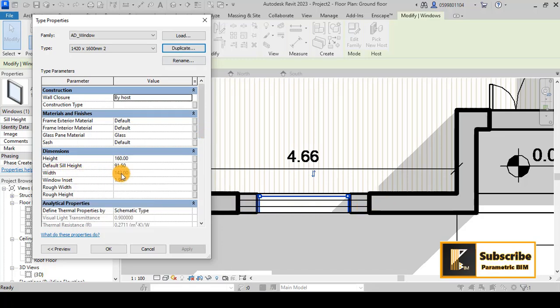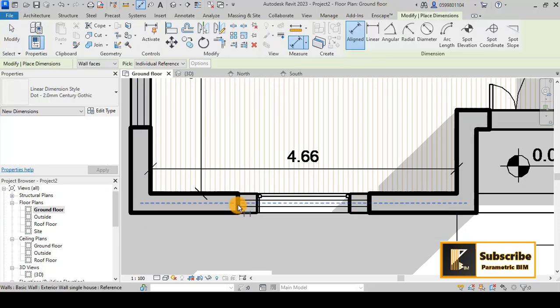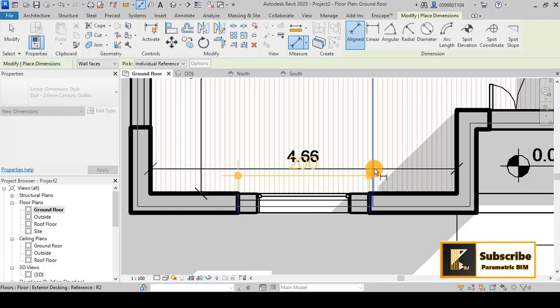Okay, and you can now play with the dimension or the width of the window. So I have here this window which is 142, but you now have to have the information or the knowledge about the width of your window. So I will go back and then go to annotate, and let's measure from here to see that our window is 2 meter or 200 centimeter.